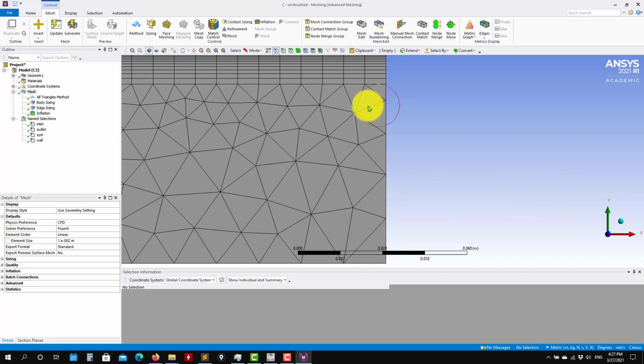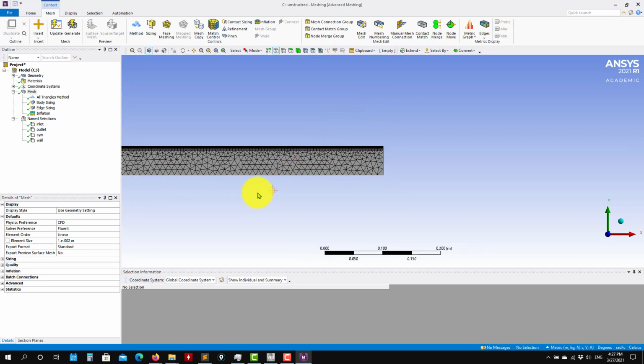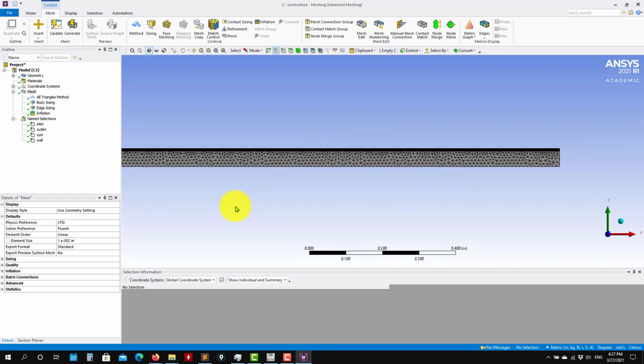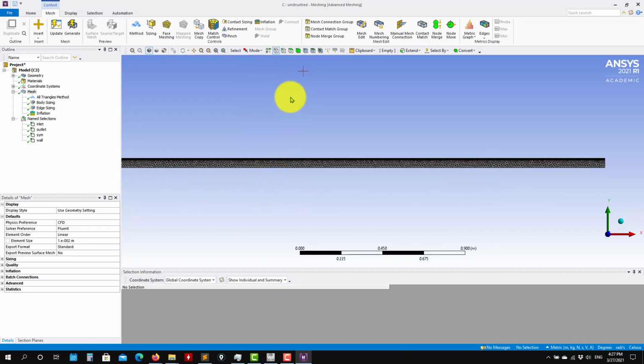You saw that this workflow is much easier than the structure one. The structure, even the structure was easy, but imagine that now you have more complicated geometries, and not even more complicated. Imagine that you have a T, another pipe coming here. Just getting that pipe in a structure mesh is tricky. Instead of structure meshes, just give global and local parameters, grow the boundary layer. So we're going to do something like that in tutorial 3 and 4.